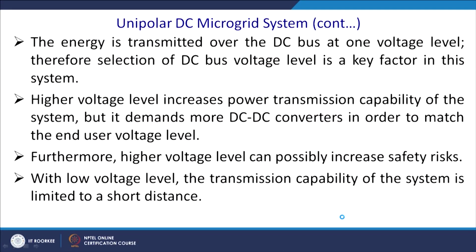The energy is transmitted over the DC bus at one voltage level. Therefore, selection of the DC bus voltage in this case is the key for the total design. Whether you will have a 220 volt RMS equivalent voltage, or 48 volt, since the battery will be around that voltage level, we have to calibrate carefully and see.